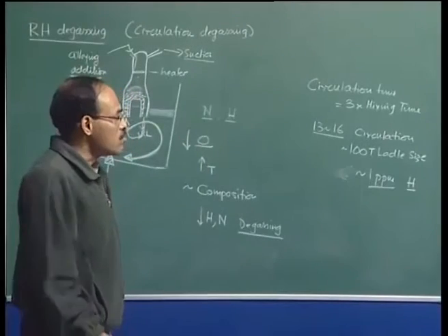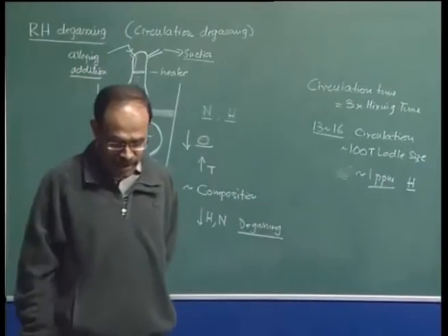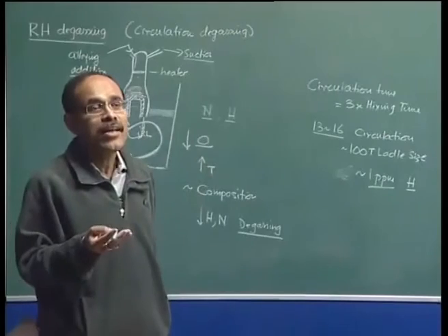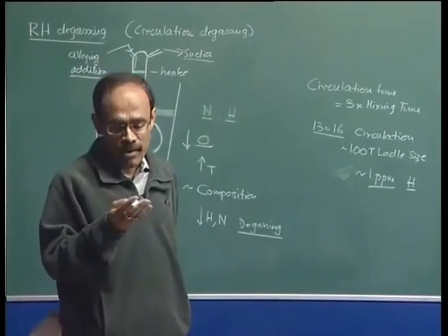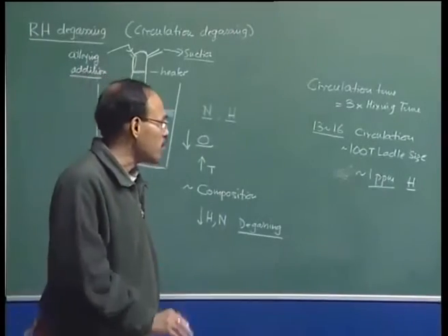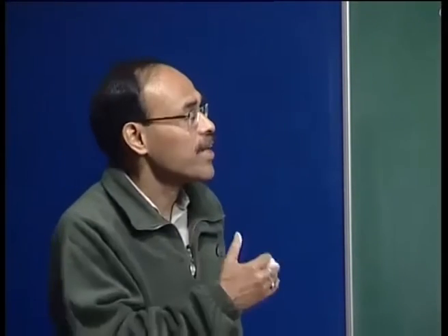Desulfurization, we all know that blast furnace is the ideal place for removal of sulfur, because blast furnace provides us with a relatively basic slag. It has extremely low oxygen potential, or highly reducing environment, and also we have relatively high temperature, which is thermodynamically correct for desulfurization.